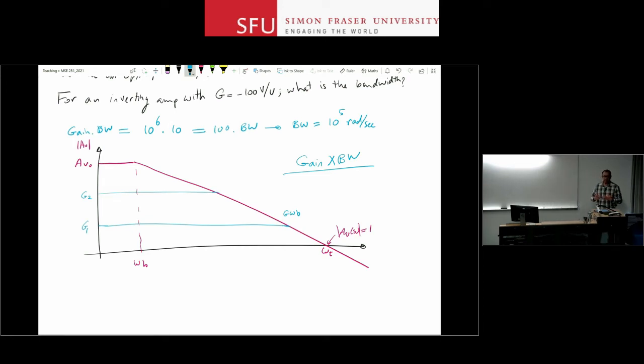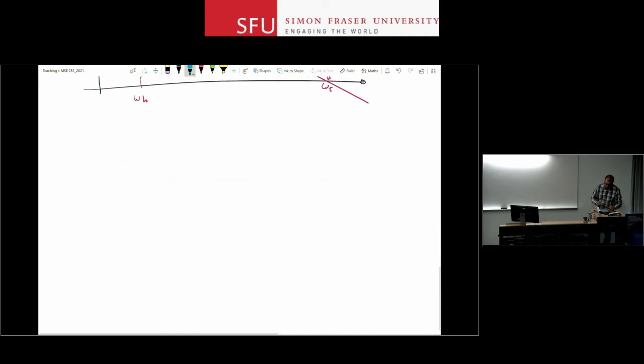There is another limitation in the speed of the op-amps that comes from what happens inside the package that is sold to you as the op-amp, and it's a nonlinear phenomenon, and it is called slew rate. It is another factor that limits the speed of an op-amp.